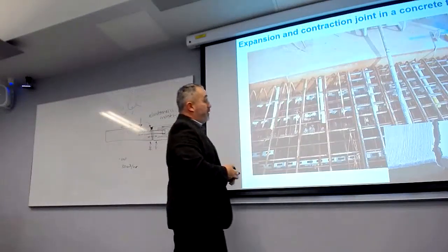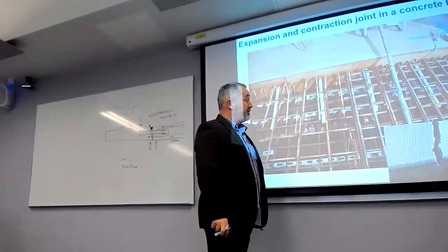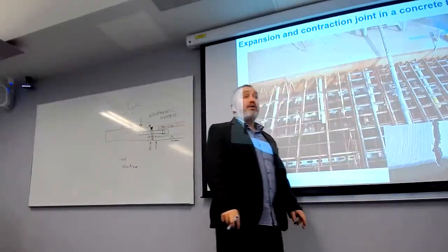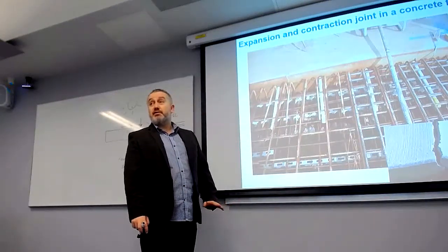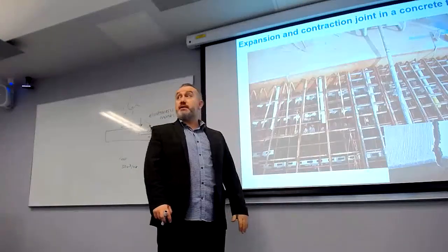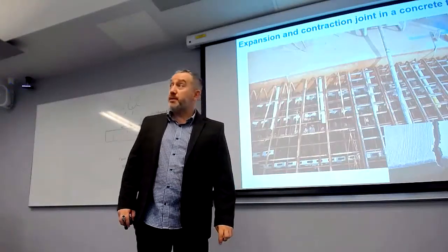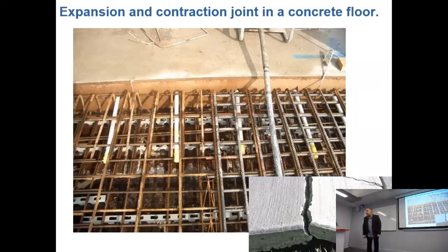That's an example of what can happen to concrete if you don't have movement joints. That's why when you walk along the road, and it's a concrete road, very noisy, you will see that there is a gap, a movement joint, every so often. It's the same in buildings. We talk about brickwork and blockwork. And I can't see any on that building, but there are movement joints on every building. If there's not, you'll end up with cracks.